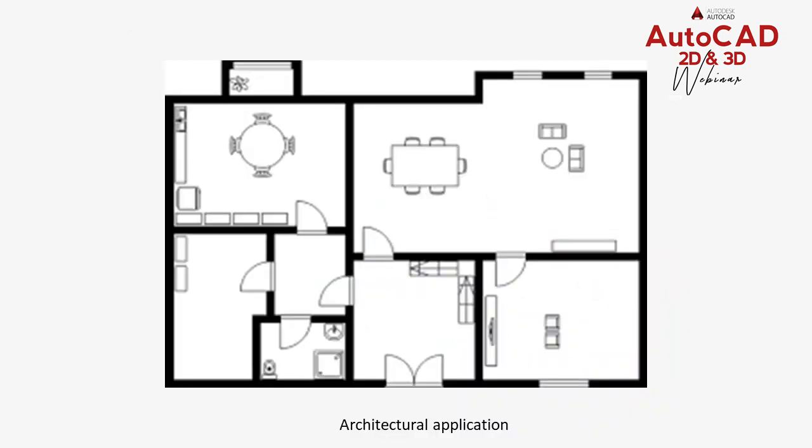So architectural application, as I said earlier on, is for your building constructions and designs. The importance of drawing is that it's going to help you save time, save materials, and even stress when it comes to supervision on the site. Because say for instance, a standard door height is about 2.1 meters by 0.9 meter. So in case someone is putting a 3-meter door there, you have to question it. In this design, how far is everything met to standard specification? So this is one of the benefits.